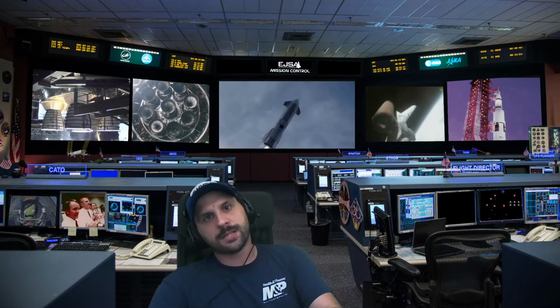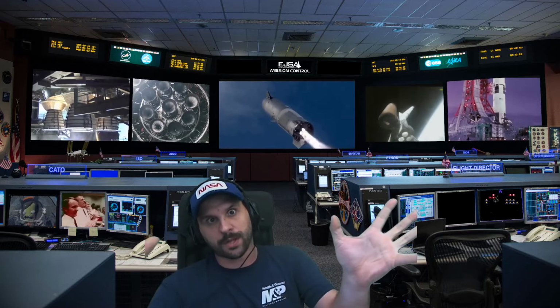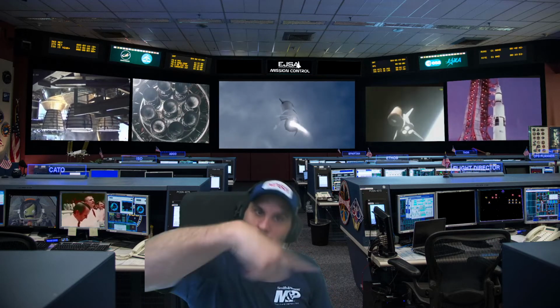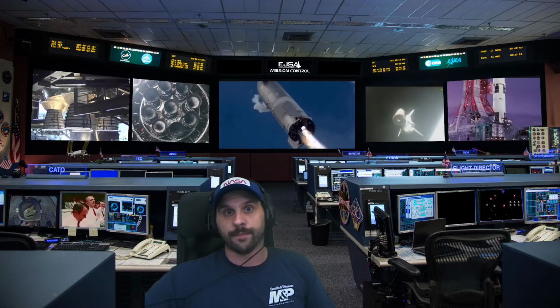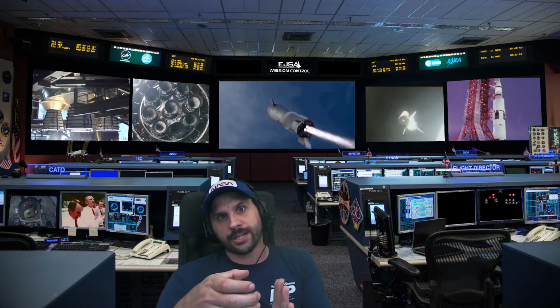What the TTAB is designed to do is get the turbo pumps going. It's that huge explosion, and it happens in the turbine. It's a huge explosion to get the turbine spun up fast enough to start pumping fuel into the engine. Rocket engines have jet engines attached to the side.